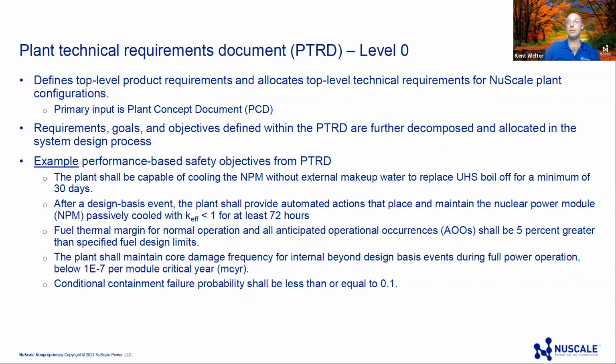First one is the plant shall be capable of cooling a NuScale power module, as our reactor, without external makeup water to replace ultimate heat sink boil off for a minimum of 30 days. So that's a very specific requirement related to cooling the reactor, and no makeup to our ultimate heat sink for a specific amount of time. So that's a quantitative safety performance objective. And there's other ones here.